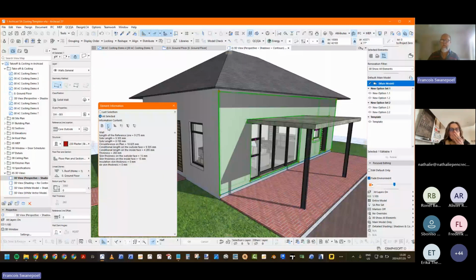So we switch that off, then go to the next one. Here you get distance values, length values, height values. That's mainly your length on all the different sides of the wall, the thickness of the wall. So these are linear information about length. Switch on the next one, you get your area, and that's your clear intersection on plan. When you switch off the next one, you'll get your height values and your different skin heights on the inside and the outside of the wall.